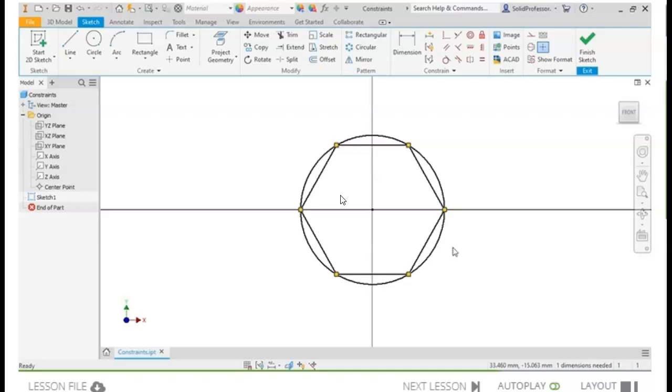With that in mind, Inventor lets you add constraints while sketching to speed up this process. For example, I'll start the line tool, place a point, and when I get near horizontal, a horizontal constraint icon appears near the cursor, letting me know that it will be automatically added if I place the line here. A similar vertical constraint appears if I move up, and once I've added a second point, you can see a perpendicular flag appears when applicable.